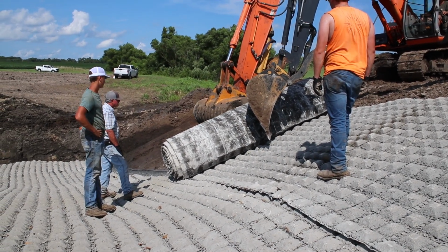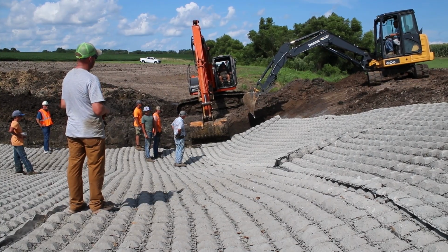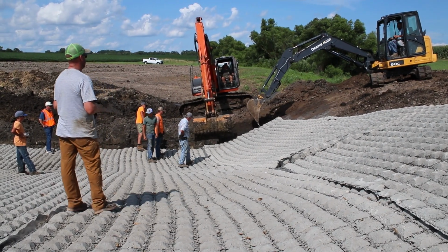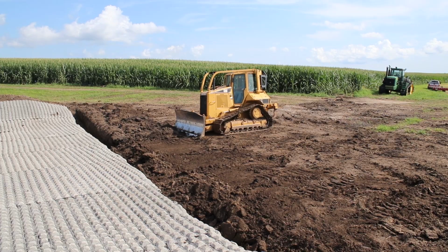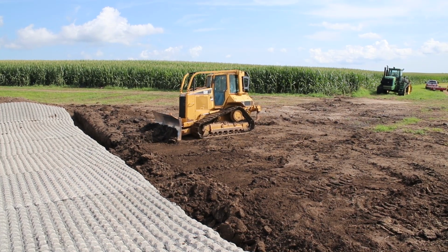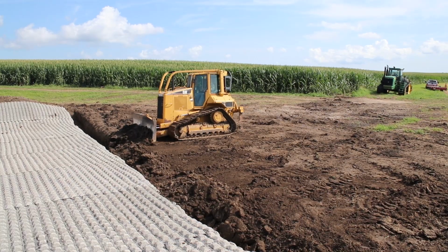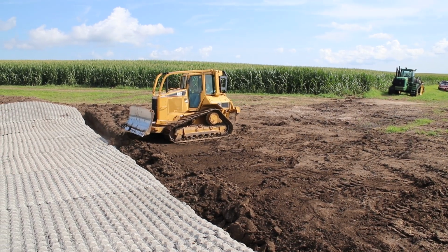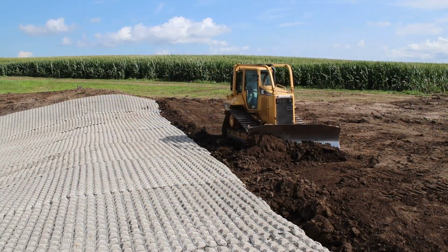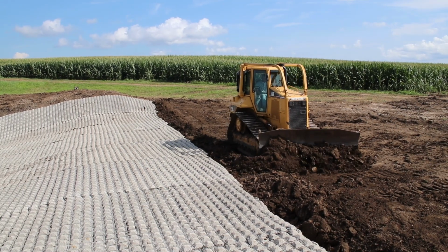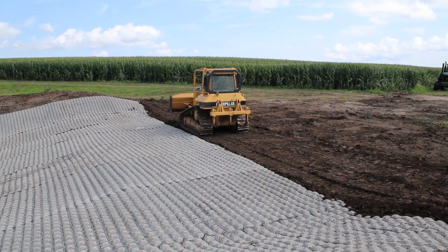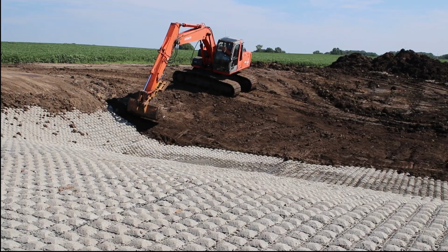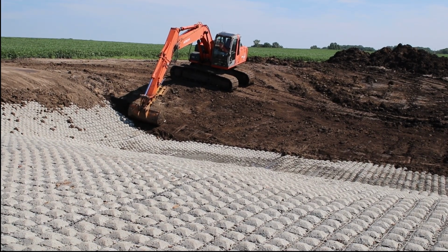The last roll also does not have the 12-inch extension flap that the others did, since there won't be another roll being placed adjacent to it. With the mats installed and laid into the trenches, both the inlet and the outlet apron trenches were backfilled and compacted to hold the mats in place. The proper installation of these trench anchors is not only important for holding the mats in place, they also prevent water from getting underneath the mats at the inlet apron and protect the outlet apron from downcutting of the downstream